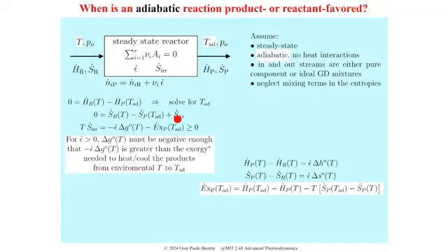And you can write this S dot irreversible. One way is to write it this way. Yes, here it is. You essentially add a zero. You add the entropy balance, I'm sorry, the energy balance, which is zero, so you can add it. It doesn't change the entropy balance. And you multiply the entropy balance by T so that it becomes dimensionally an energy.